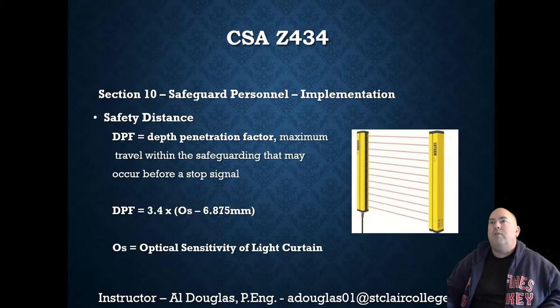Now, depth penetration factor is basically how far you can put your hand, or any part of your body, through this light curtain before it even realizes that you've put something through the light curtain. What that is dependent upon is the spacing of these beams.